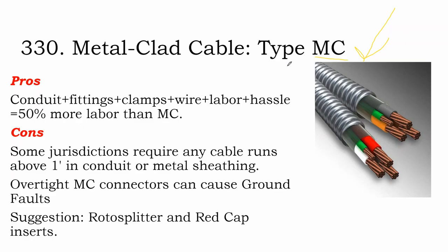So when can you use metal clad cable? Some jurisdictions don't let you use this. I'd say if you're in a major city on the east or the west coast, multi-unit building, they might have a requirement to say, no, we want you to use conduit that's a little bit stronger than this metal clad cable.